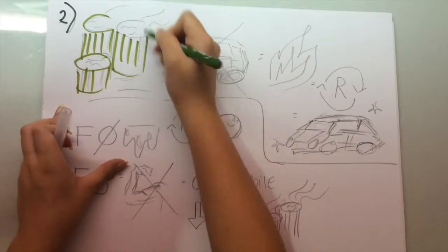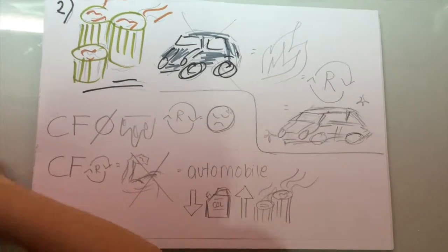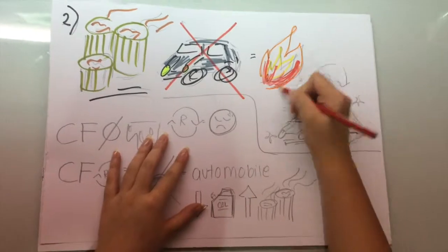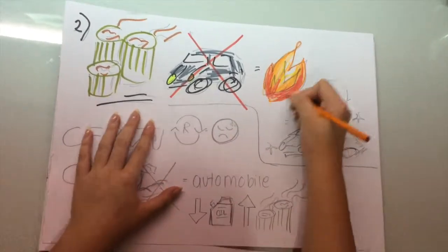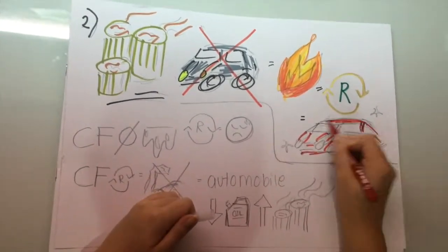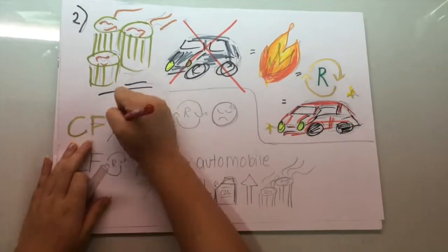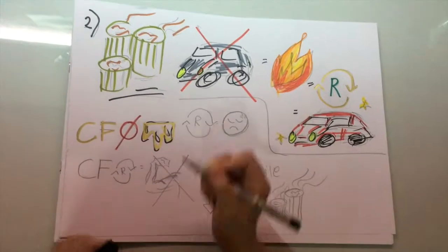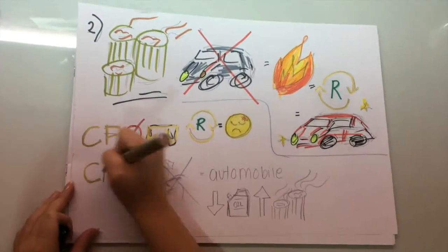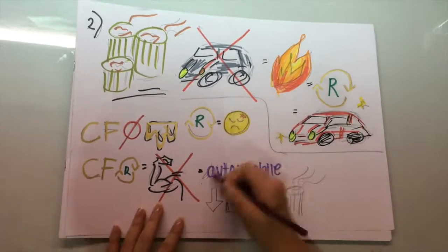However, the limitation of this material does not end economically. Another obstacle standing in the widespread use of carbon fiber is its waste disposal. Typically, cars that have broken down would be recycled through the melting of scrap steel, and that would then be used to make another car or any other object made of steel. Carbon fiber, on the other hand, cannot be melted, and recycling this fiber is not as simple. And even if the material is recycled, its strength will significantly decrease from its previous use, and would certainly not be strong enough to construct a new car.